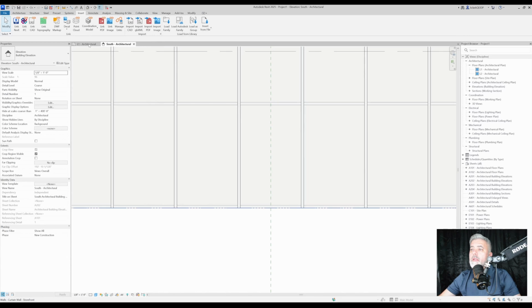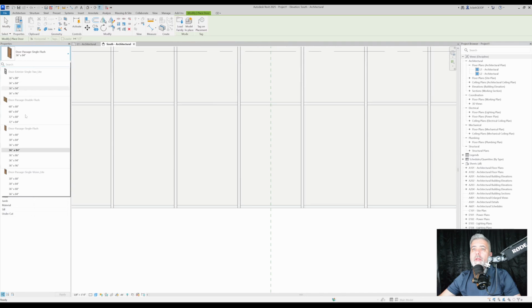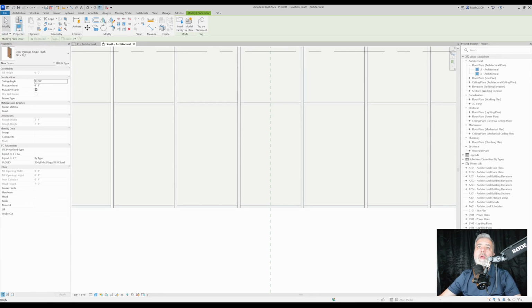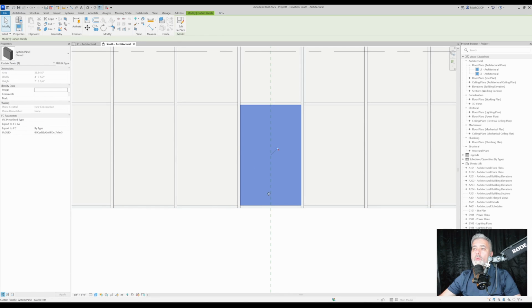It's sitting there now. Now, if I click Doors right here, notice that it's not loaded up here, okay? Through my whole list, it's not here, okay? That's because, yes, it is a door category. However, you have to remember, we're replacing the panel. We're not actually placing a door per se. We're switching out the panel. So I must click on the panel.